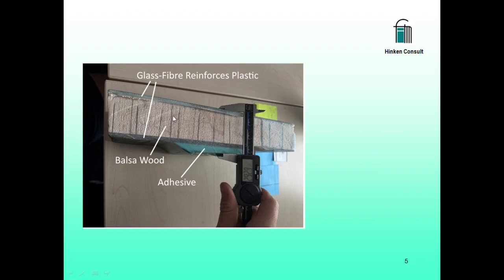The laminate can be 40 to 50 millimeter thick, and the task is to non-destructively test from outside the adhesive layer inside for air voids. Because all the material is insulating, microwave testing is a good choice.